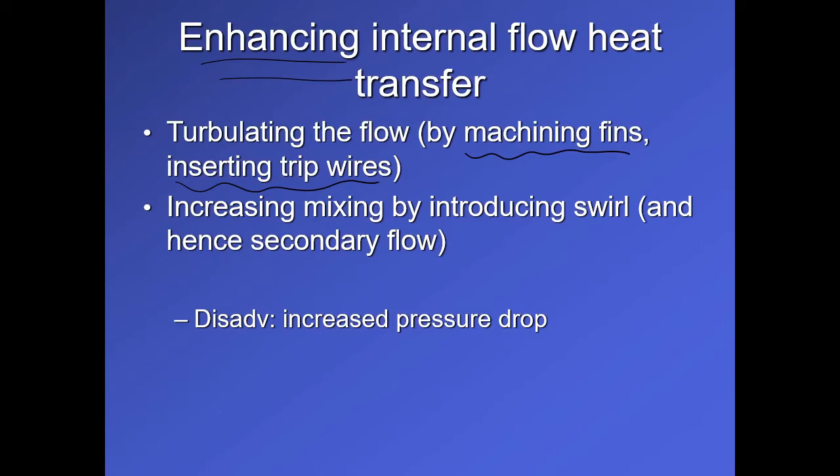The other thing that is done is introducing secondary flow in pipes. Since you have to give the fluid some time to flow in the pipe, instead of having a simply straight pipe, you can have a helical pipe, something like this, like a spring, but this is a pipe in this case.